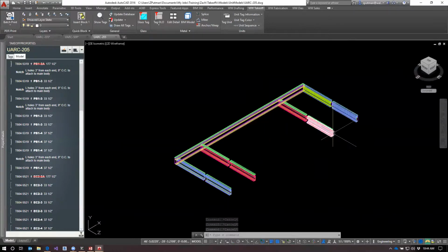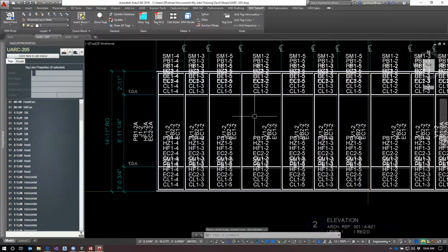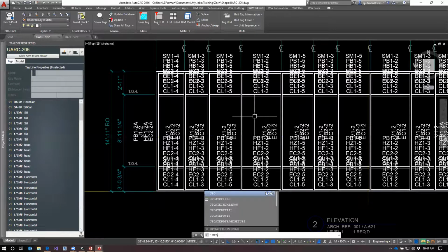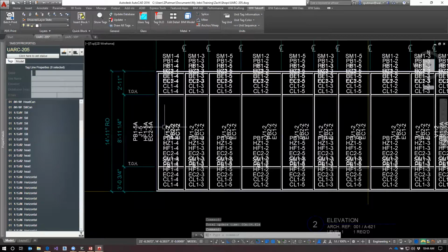Yeah, let me do that. Let's demonstrate that. So I'm just going to close this. I'm not even going to save it because I already did save it. I'm going to re-UPD this so that my jam has the right length. I'm expecting these mark numbers, all 4 of these, to change because all of their lengths just got bigger. You see they're all 5s and 5As now.